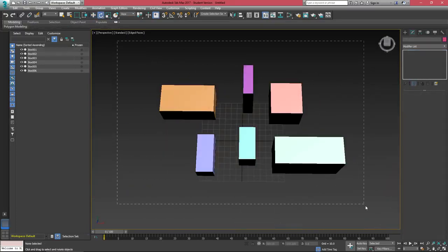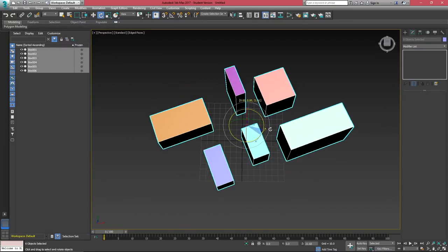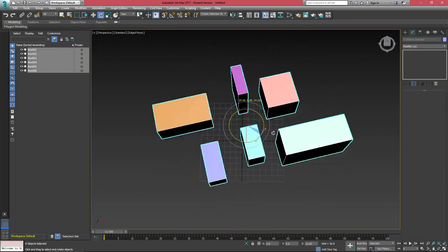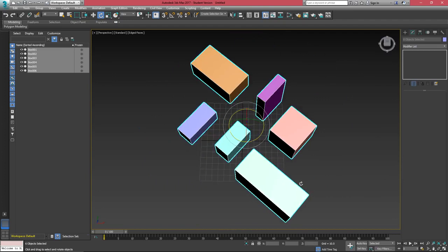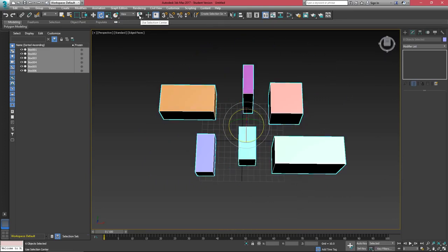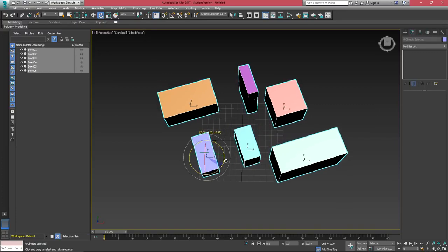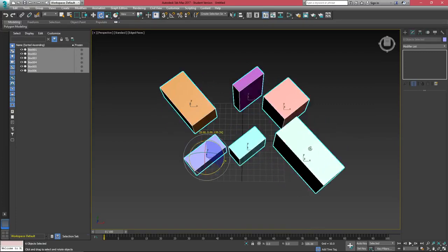If I select all of these objects here and use the rotation mode, they're rotating along the center of the selection. We can see this by the plus sign on the two boxes for Use Selection Center. If I change this to be the multi-pluses on each box, this will end up rotating each of these objects along their local pivot point.